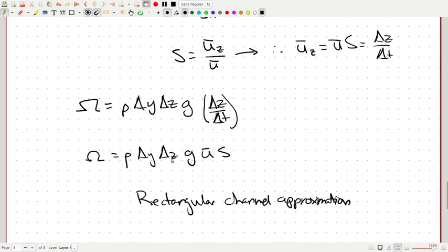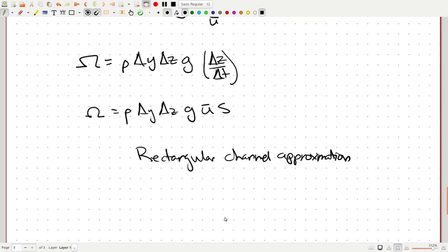And in this, we say that our control volume is not just some random volume, right? So we had this delta x, which was the distance downstream through the cross-section, but we've been talking about the full cross-section the entire time. And so what we're going to say is that we're thinking about a river channel where we can approximate it, just like we did when we discussed flow velocities, as having a rectangular base and vertical walls.